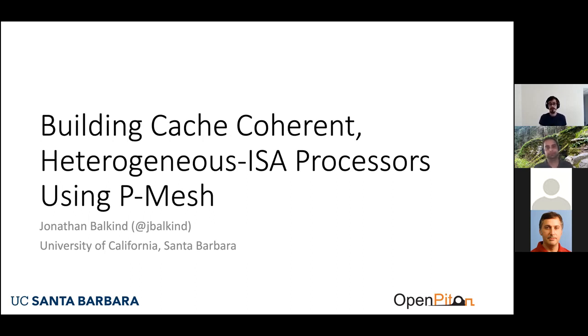We could instantiate more cores on either side, and those are independent domains from each other with respect to all IRQ related stuff, right? So if you want to signal to the other core, you would have to do that via shared memory with the way that we have it set up today. We have a mechanism we've been building internally to allow an IPI that could go across ISA, but we haven't built all the software support on top that you would actually want to make use of. But cool, this is very neat stuff.